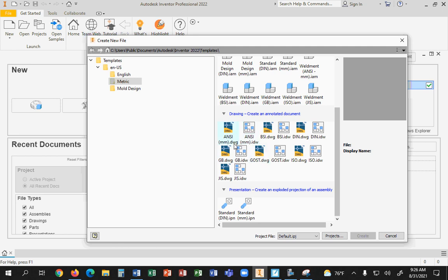On the detail drawings, they let you go both ways. Are you going to create a detail drawing so it's a DWG file so somebody who's using AutoCAD can also open it? Or are you just going to go ahead and do it as an IDW, which is an Inventor drawing file, and detail it there and then send it to somebody as an AutoCAD file after the fact? Doesn't matter. Depends on your company. Your choices there.